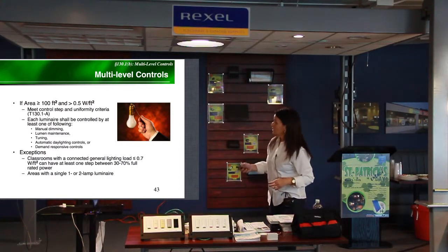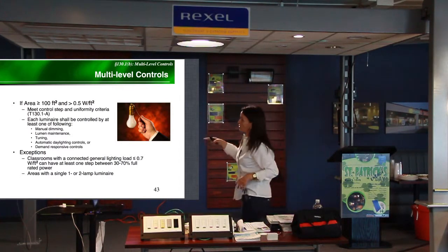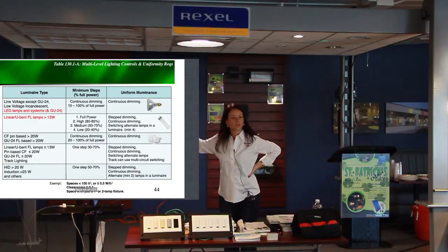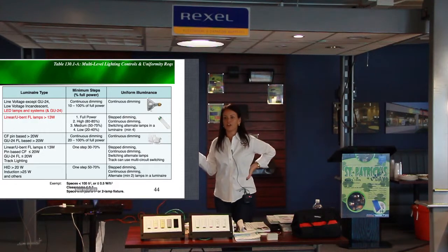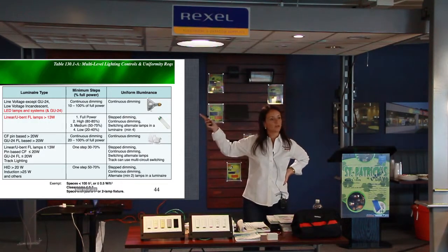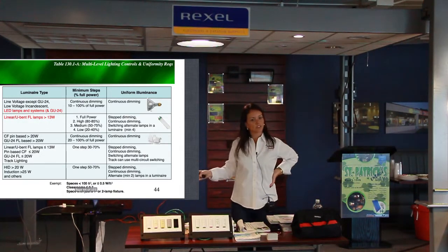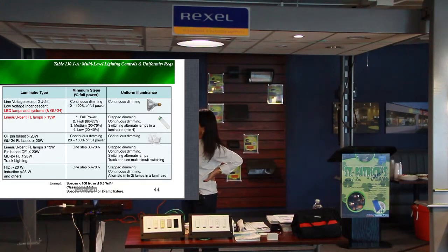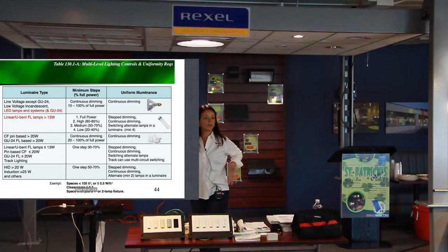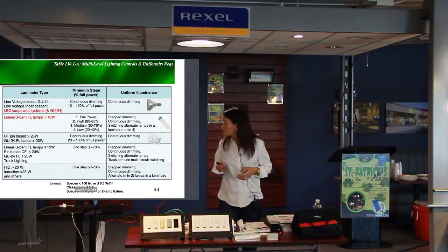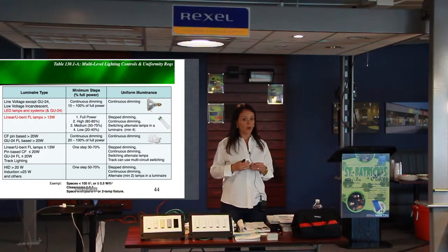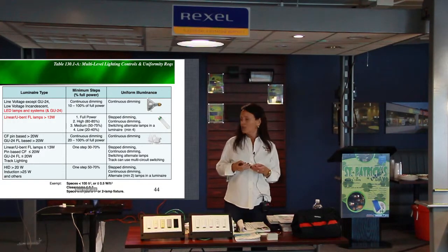Now, you have to follow the table 130.1(a), and that's the table. I think every fixture manufacturer from now on will have some kind of interpretation of this table. Probably the most relevant ones are these 2 lines. I will start with linear, higher than 13 watts fluorescent. A lot of applications, commercial spaces.